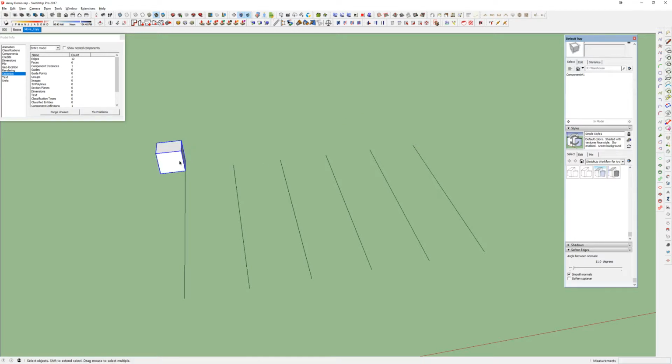Another way of looking at this, so that's moving it, placing it, and then adjusting. The other way, if I put it back to its origin, is I can start to move. I do not left click, so it's still attached, it's still moving, but I'm on the axis I want to move it. I then can enter a distance, let's say 360 for 30 feet, and it moves it 30 feet. And then just like before, I can come back in and adjust where I'm pushing it. And all I'm doing is just entering different distances. Does that make sense?